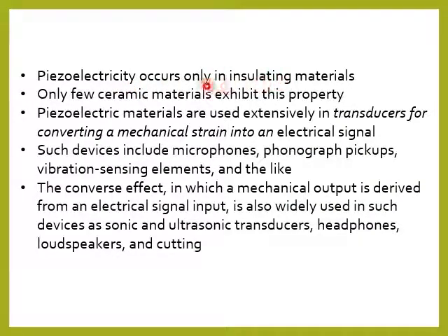Piezoelectricity occurs only in insulating materials. It does not take place in electric conductors. Only a few ceramic materials exhibit this property. Piezoelectric materials are used as transducers. Transducer means they convert one form of energy into another form of energy. This type of transducer converts mechanical strain, which is applied on the piezoelectric material, into an electrical signal or voltage.